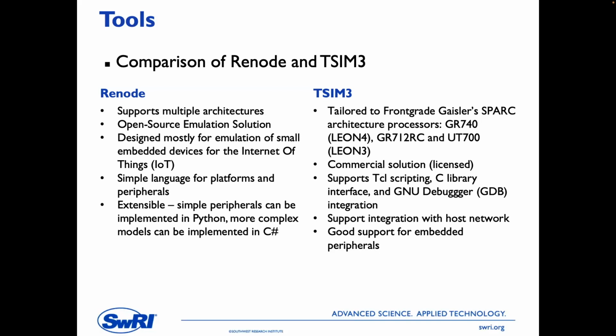TSIM, on the other hand, is set up using Tcl scripting. So for those of us that are familiar with Tcl, it has good support for that. It also has a C library that can be used to control it. And it also has very good support, especially now with the newer versions of GRMON. We were showing GRMON 2, but with GRMON 3, they have good support for the GNU debugger. So you can do source level debugging through TSIM.